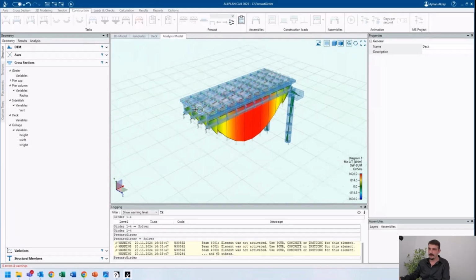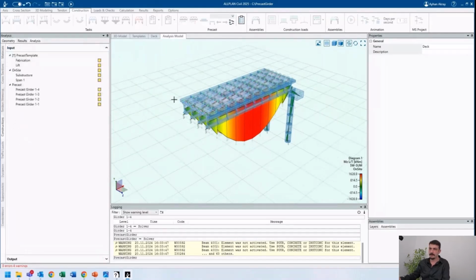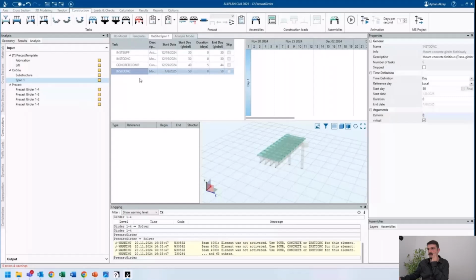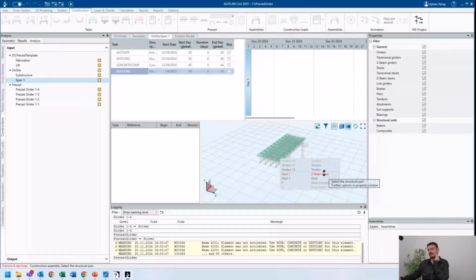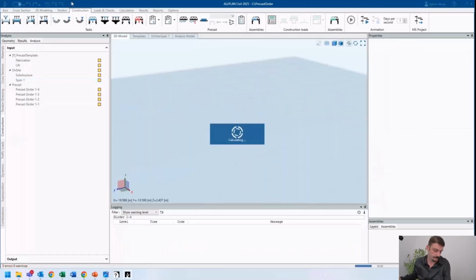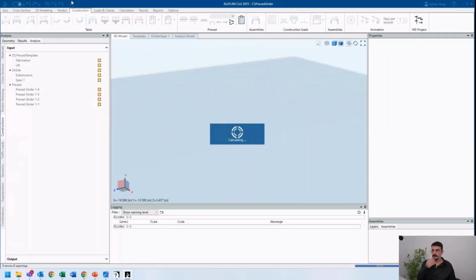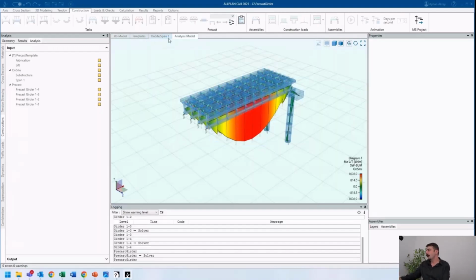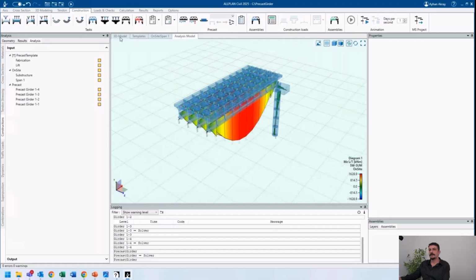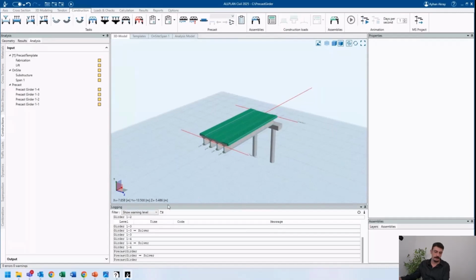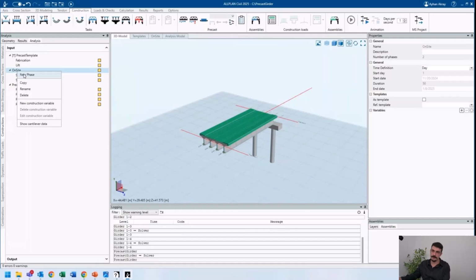So this created a new beam in the transverse direction, by using this function, by using the assembly known as Z-beam deck. Press enter and rerun it again. And after activating it, we see no warnings, and we can continue to assign additional loads to the system.